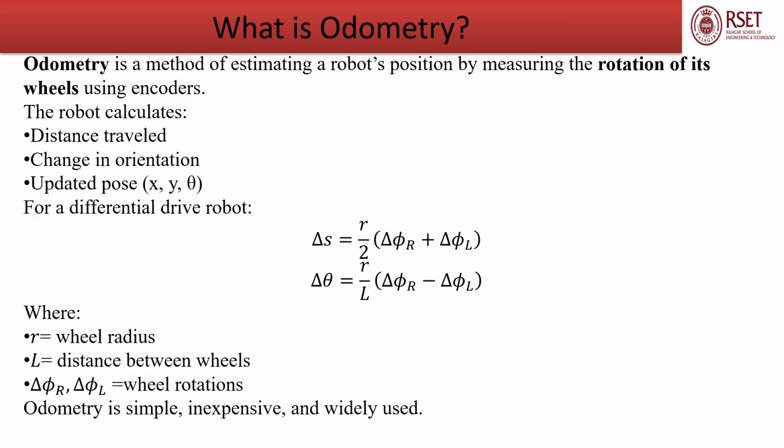It is computationally simple and does not require heavy processing. That is why odometry is widely used in indoor robots, warehouse automation systems, and educational platforms. However, odometry has an important limitation. It assumes perfect motion execution. In real environments, that assumption rarely holds true. Even small imperfections in movement begin to accumulate. So, odometry gives us a continuous estimate, but we must question how long we trust it.